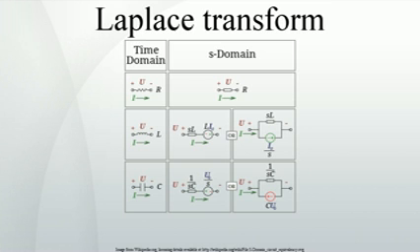This is the precise definition of the unilateral Z transform of the discrete function x[n], with the substitution of z equals e^(sT). Comparing the last two equations, we find the relationship between the unilateral Z transform and the Laplace transform of the sampled signal. The similarity between the Z and Laplace transforms is expanded upon in the theory of time-scale calculus.